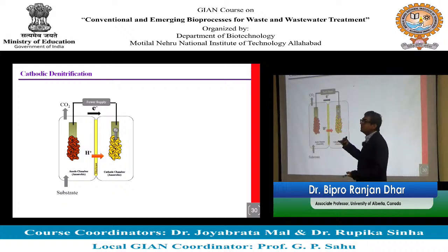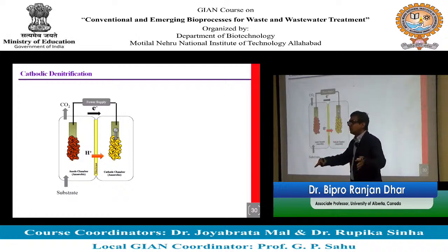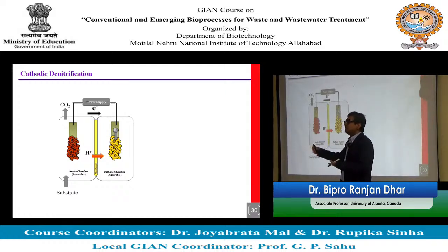So you have in situ hydrogen production, and the cathode feed is going to be maybe some wastewater coming from your aerobic or aeration tank, where you already converted ammonia to nitrate. Then you have denitrifying bacteria, you have nitrate from the wastewater, you have hydrogen from the cell, which is the electron donor, and you have the electron acceptor nitrate, and you can have denitrification.